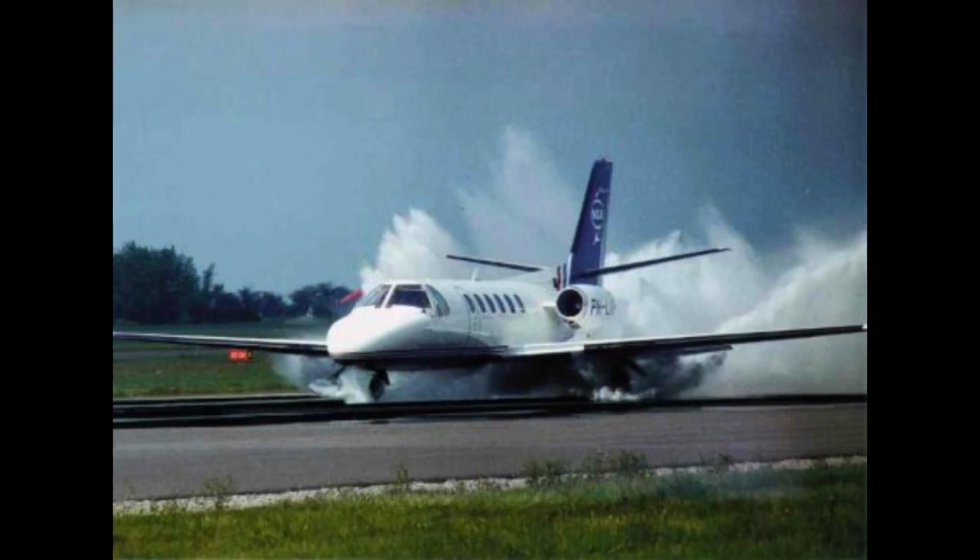Hydroplaning is a condition that can exist when an airplane has landed on a runway surface contaminated with standing water, slush, or wet snow. Hydroplaning can have serious adverse effects on ground controllability and braking efficiency. The three basic types of hydroplaning are dynamic hydroplaning, reverted rubber hydroplaning, and viscous hydroplaning. Any one of the three can render an airplane partially or totally uncontrollable anytime during the landing roll.